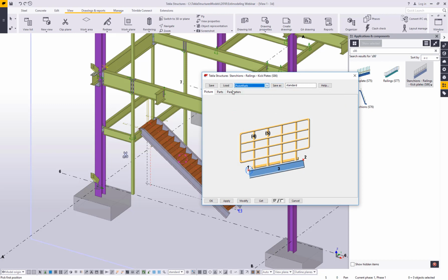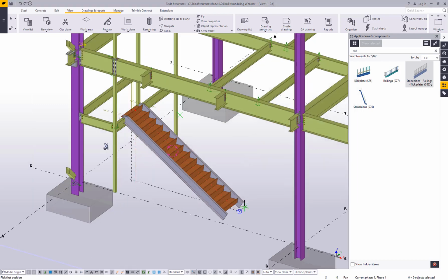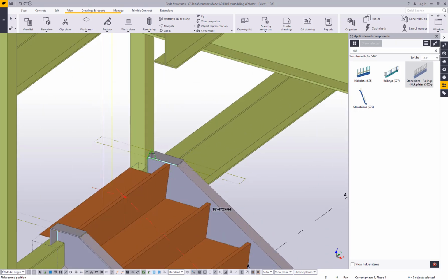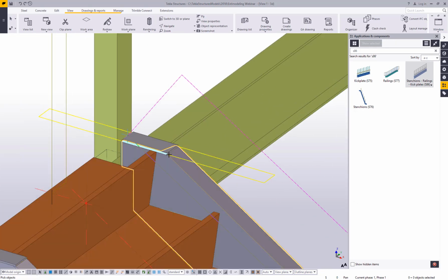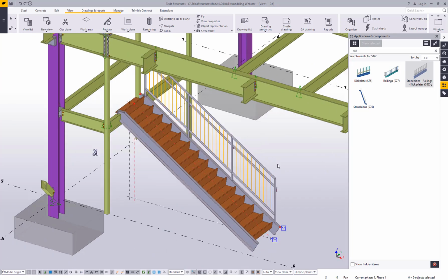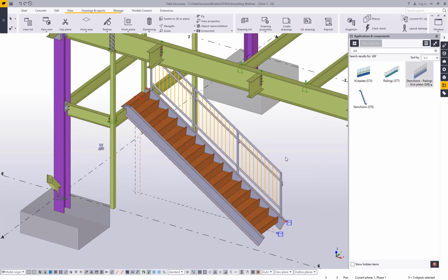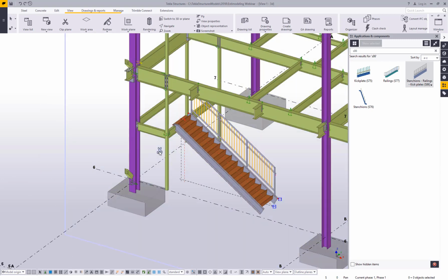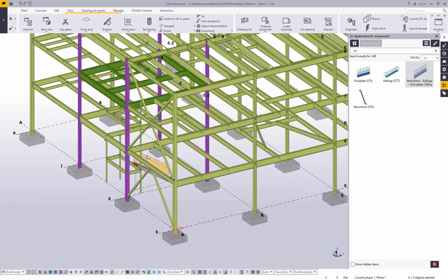But just to also show, if you needed to, you could very quickly throw in something like a picket rail. Just by picking 2 points, selecting the objects that I'm trying to connect to, and that quickly I can, again, create, just for estimate purposes, a quick handrail. So there's a lot of tools available here to show all of the information in the model as much as you want. If you wanted to show things like pour stops, we've got things for pour stops.